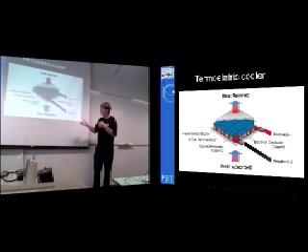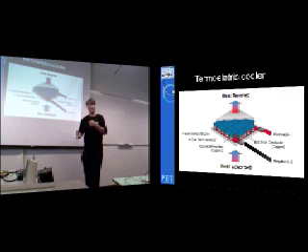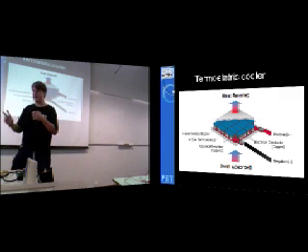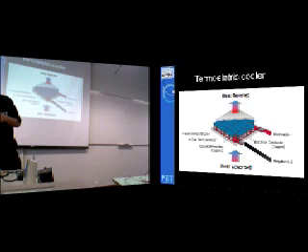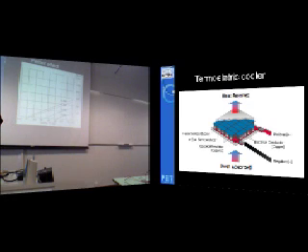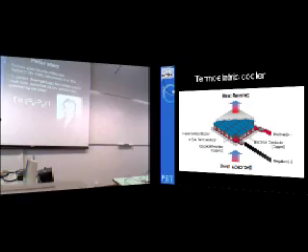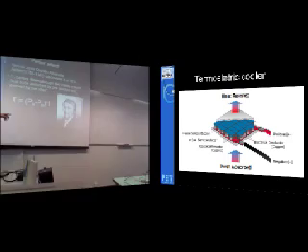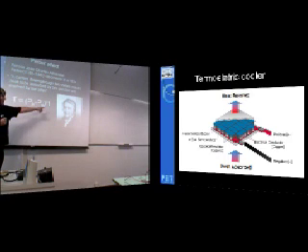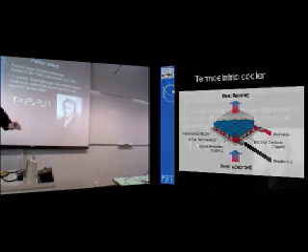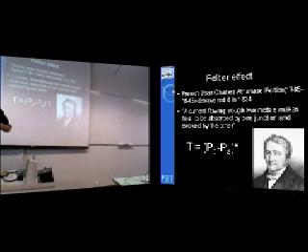But one thing is still to be said about the thermoelectric cooler: it can be a cooler and a heater at the same time, because if you remember the formula of temperature, if this current here is negative, meaning I'm driving the current the other way, the difference will be reversed.